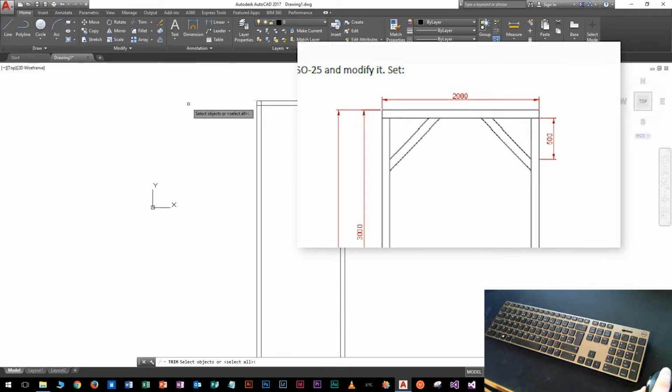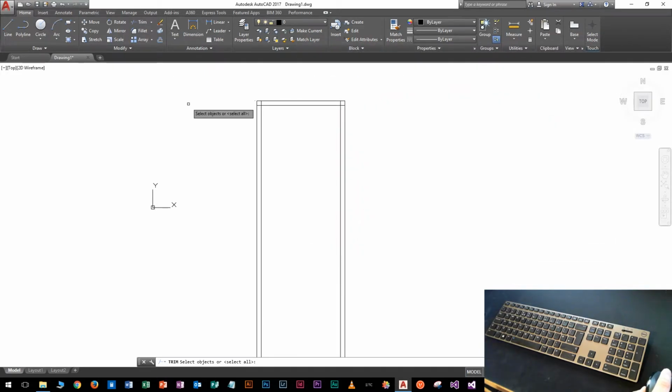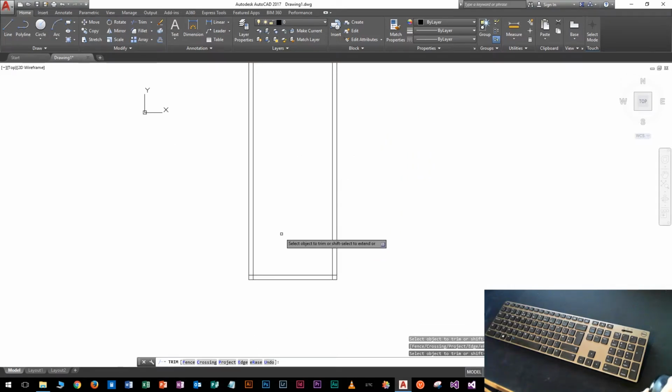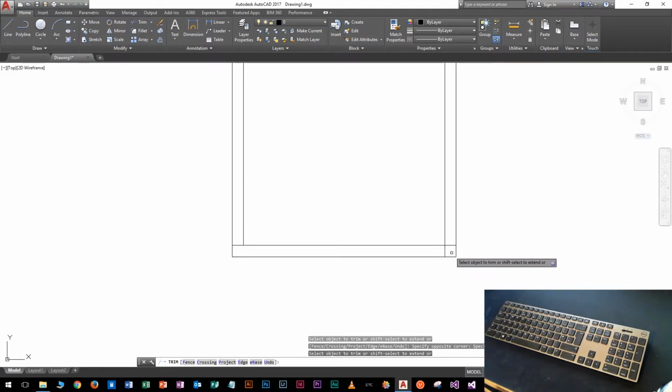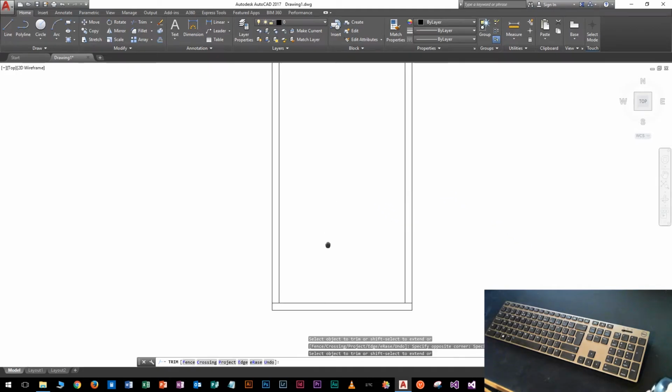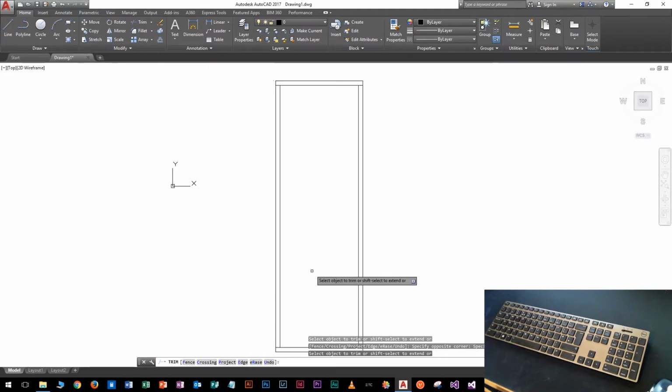So we're going to go up to the trim tool, and remember, first click is left, second click anywhere on the page right, and then we can just trim these out by using left click. Brilliant. Okay, so the next thing we need is this cross brace.